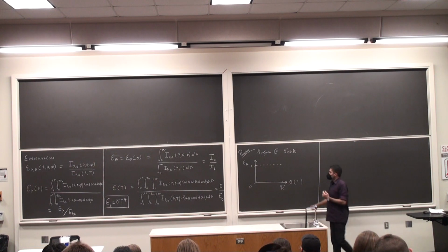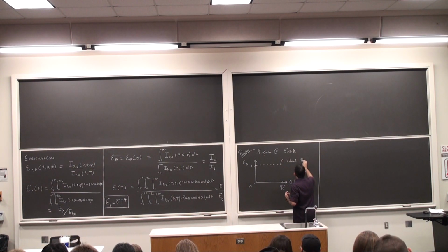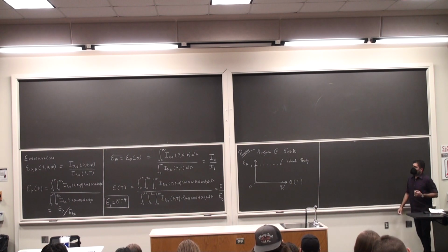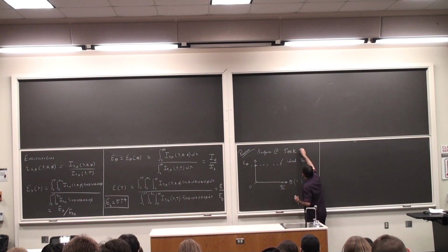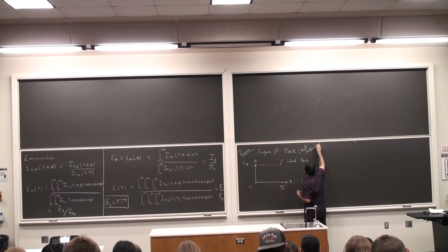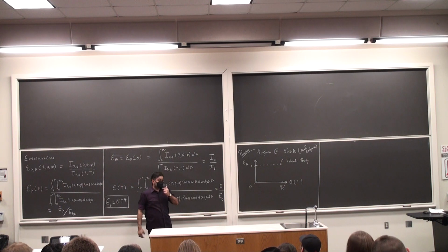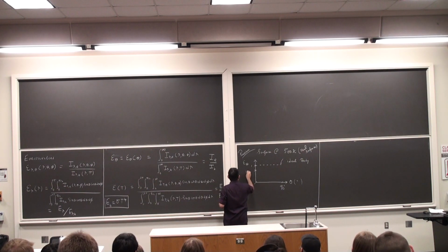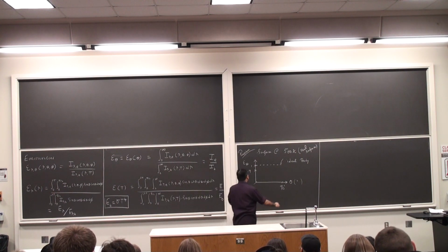This is for an ideal body. For an ideal surface. What I'm saying is, for the surface that we have, this is the real surface. The directional emissivity is given as the following. It's equal to 0.9 from 0 to 75 degrees, and it's 0 after that. So 0 to 75.